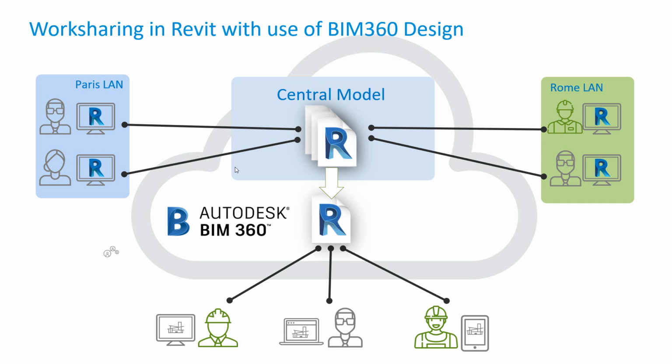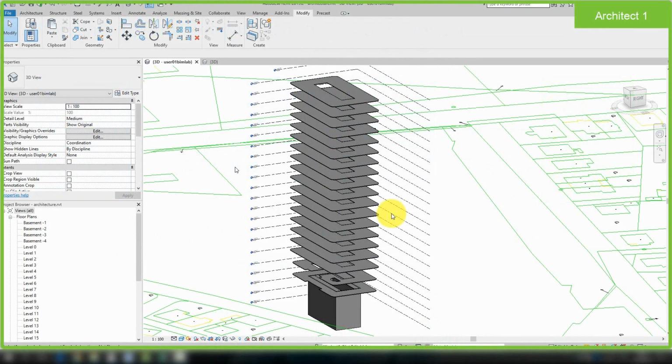You're opening a Revit model in a browser, which means that of course you cannot modify, so you cannot add a wall in the browser version of your Revit model, but you can comment and you can communicate and read the model without Revit, without any Revit software installed on your computer. You're just reading a Revit model from the browser. Okay, how does it work?